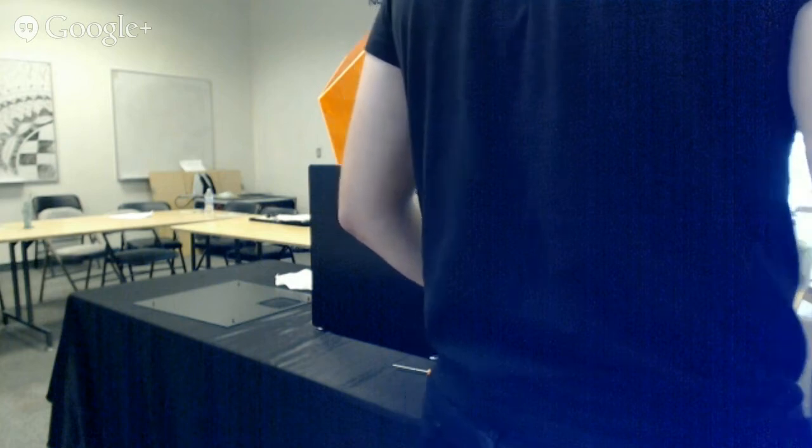Well, more than that, because this chin is concave, and so it floats out in the middle of midair over here. So there would need to be, because if you end up creating an island with resin, it would float in the middle of nowhere. It wouldn't adhere to the rest. Everything has to be attached. And yeah, you can see there's support here. The nose, for instance, this guy probably did not need any support. Maybe one tick here, but very little.